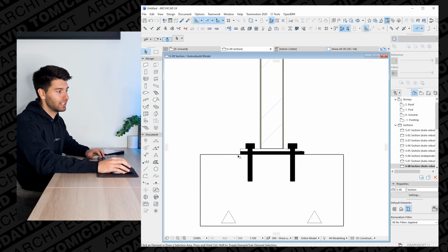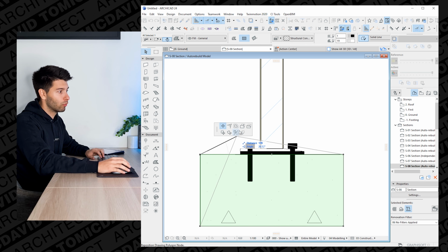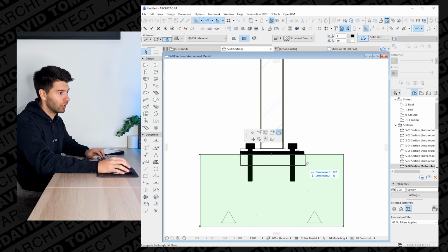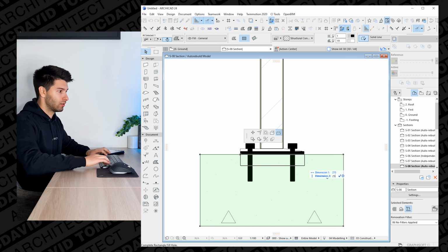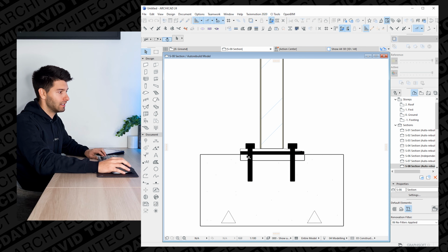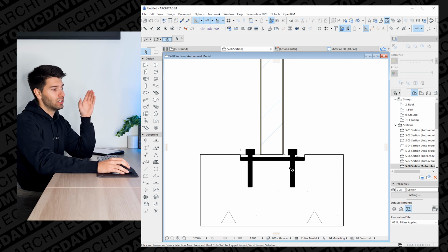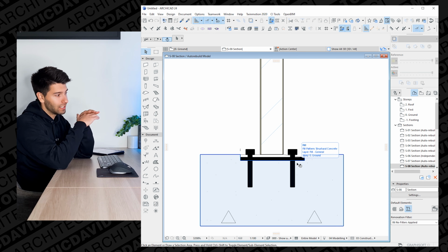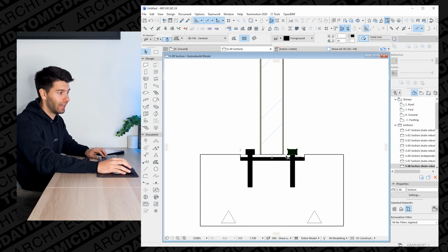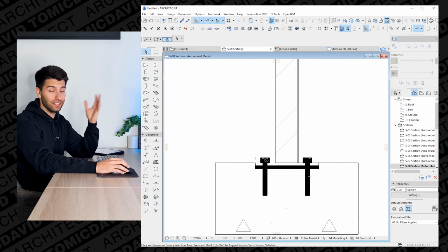Personally speaking, what a nice architectural detail would be a simple recess into the concrete footing. So let's recess that. We'll call that 25 millimeters and select all of our column and our base plate, allowing that to be recessed into the concrete. So it's a nice flush detail, and all you have to worry about then is the bolts.